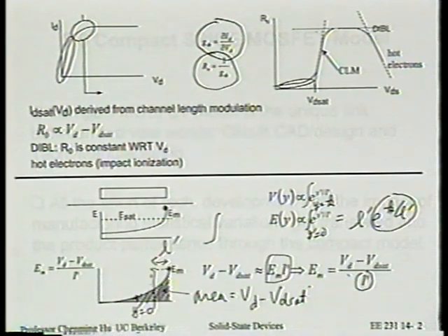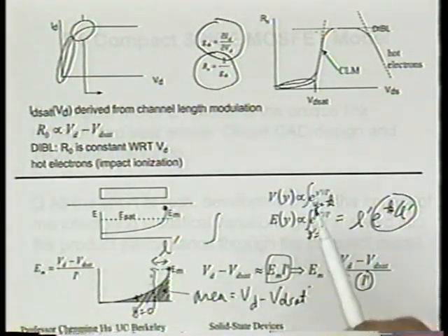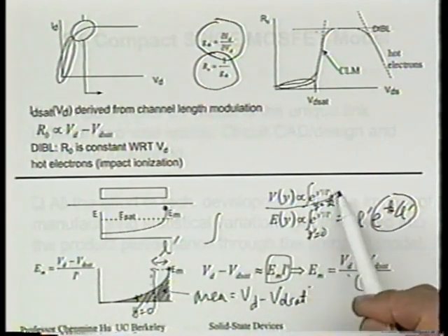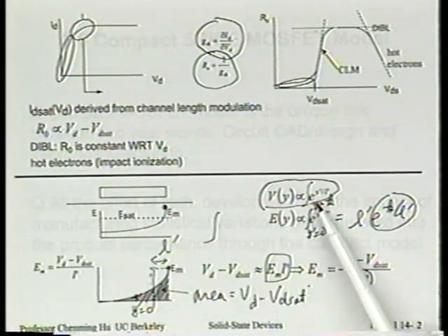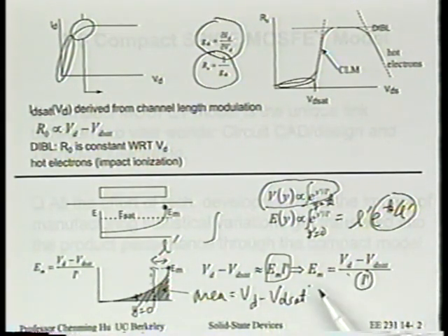For the entire channel length? Oh, no, it's not. Let's just agree: this equation is only good for the pinch-off region. This is what we derived last hour, except we wrote it down with a hyperbolic sine. Today I'm using a simpler form. So no, definitely this is only good for the pinch-off region. But fortunately, we only need to use it for the pinch-off region for today's purpose, for EM.